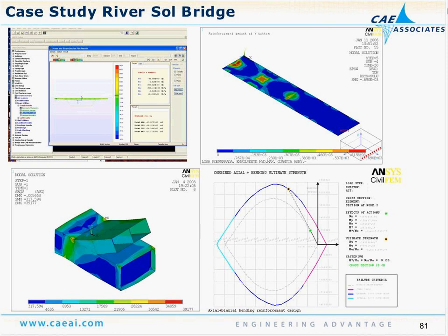In the reinforcing design capabilities of CivilFEM, you need to specify a cover and an initial cross-sectional area of rebar, but you can have the code go ahead and do a design process where it will figure out how much additional rebar is needed, for instance, if the initial guess under-designs the section.